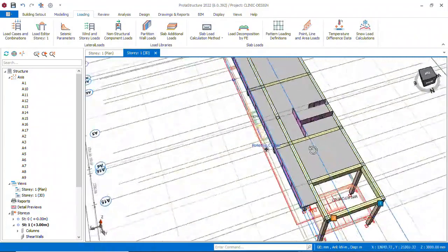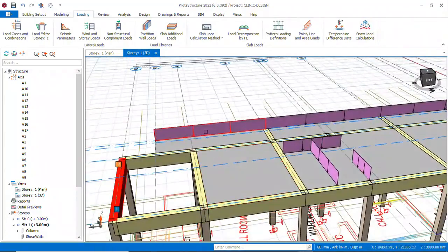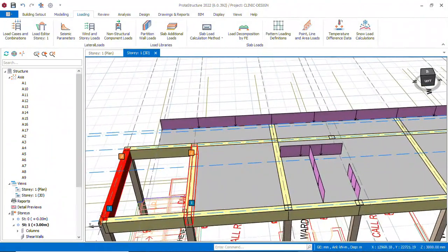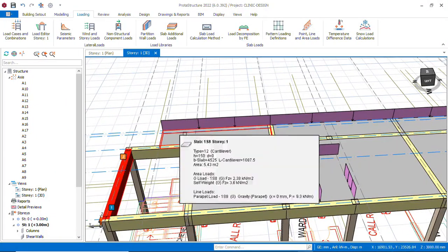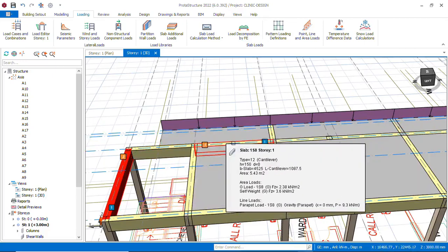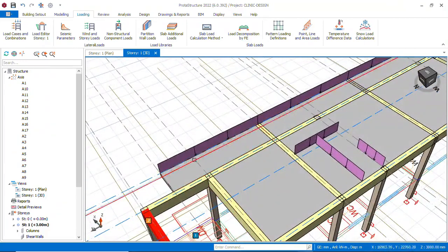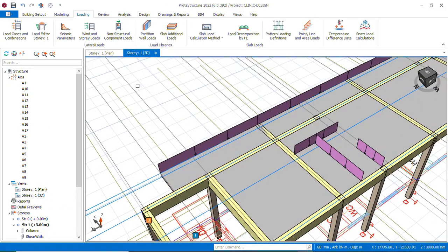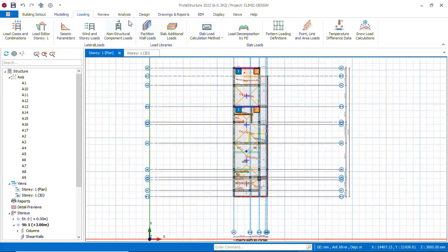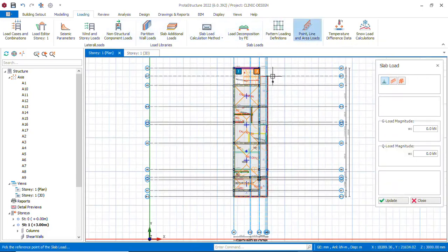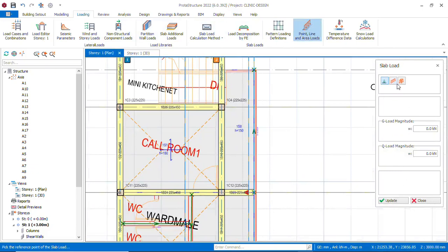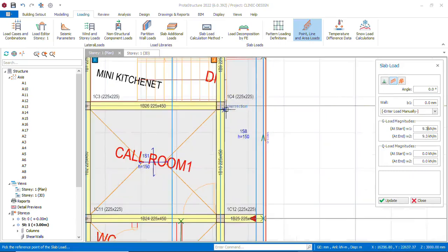You can see this is the wall load it's carrying. You climb here, you enter, you land here, then you enter. Okay, there's another wall here. There's another wall passing here where there's a door. So let's also put both loadings, point and area loads, and then pick this and then type 9.3. Okay, then have it here to here. Yeah, so you can now look at it.